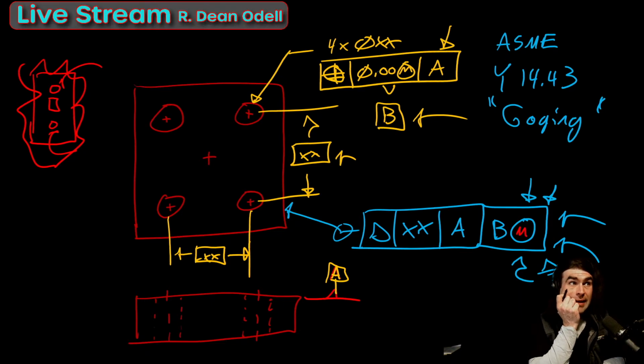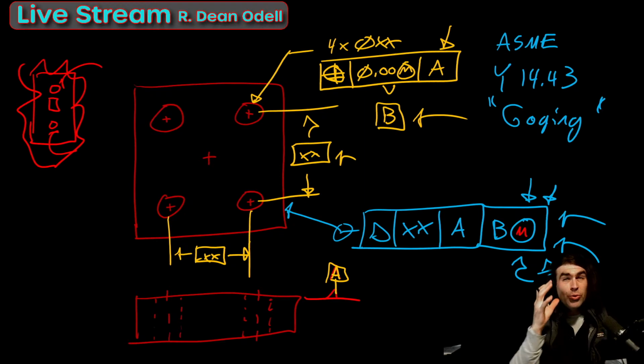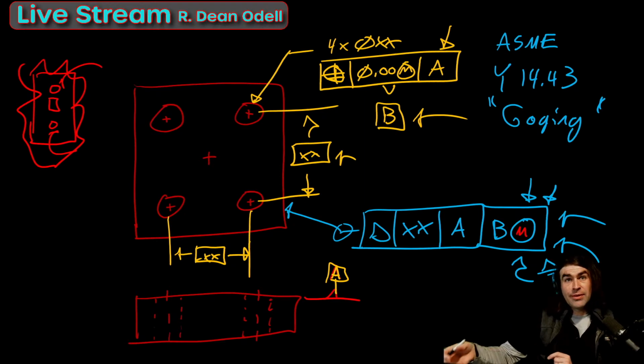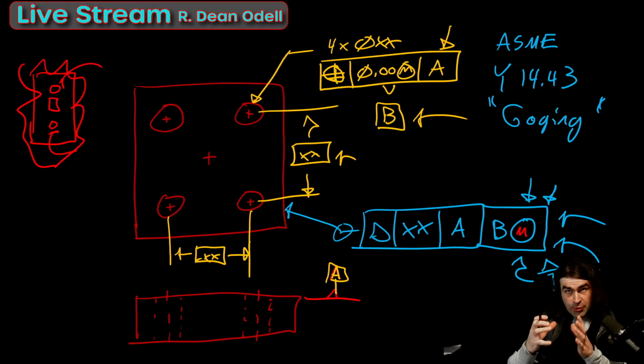And you might say, okay, well, I'm just going to check it on a CMM, so who cares anyway? Well, you could still use the pins with the CMM, right? So the idea is you make this thing with 4 pins, right? And you put it on your CMM table and you find the 0. Now you can just drop a part in there, right? And then just measure each part. You don't really have to do an alignment every time. So it can still have advantages.